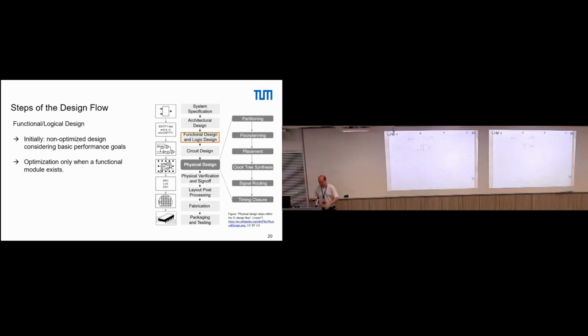For that, we now go to RTL level, and in our case it's VHDL, and we write a block that is called entity, which I give a name, and this entity has some inputs and outputs, so it has ports. Should I try to zoom better? In our case, we have specified A and B as inputs.